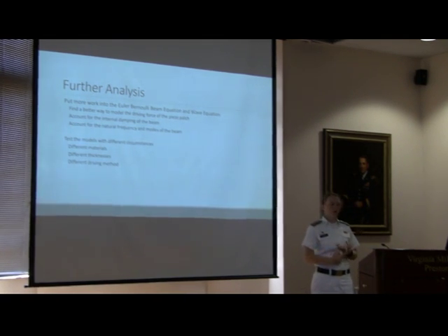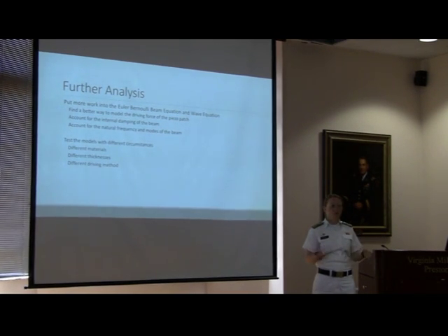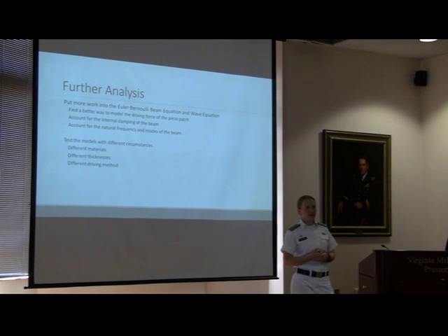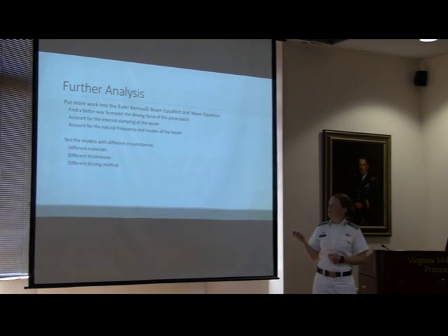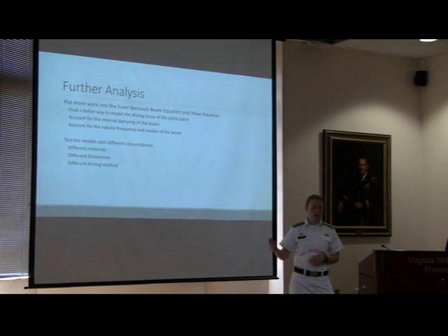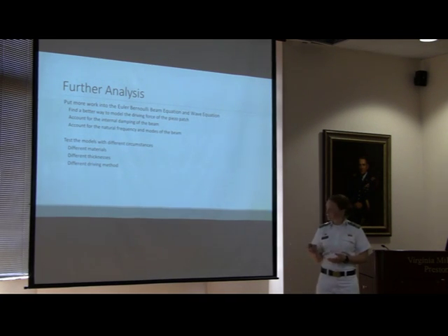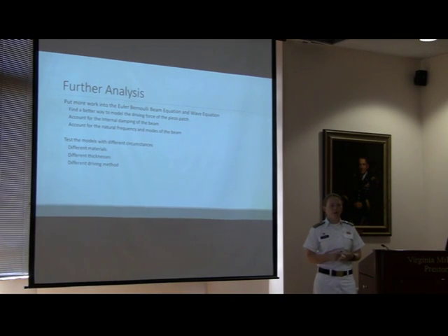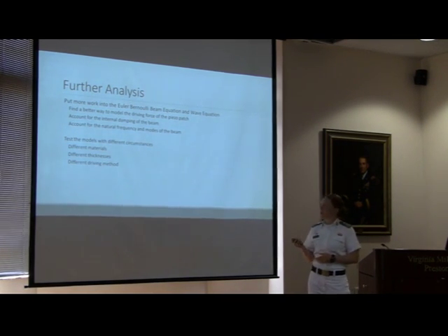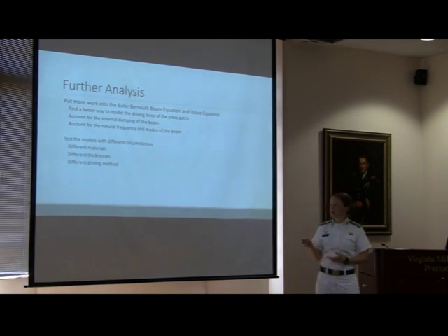Also, I'm not accounting for any internal damping of the beam or the natural frequencies of the beam. I think that is where I would like to start if I were going to keep going on this: to look at the actual natural frequencies of the beam and match up the frequency I'm measuring at with those frequencies. And then I'd also like to look at what different materials have an impact on this. We used a pretty simple aluminum alloy, but what would copper or something else do, and how well can we model that change in material in the actual models? Because I think that would be interesting to look at.